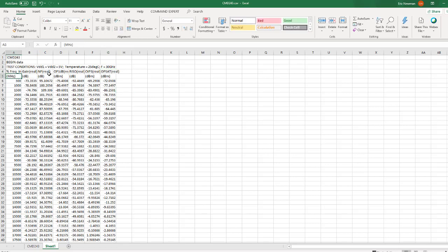Okay. Next, we're going to change the frequency range here to use hertz rather than megahertz. This is again to avoid simulator conflicts later. We're going to add that exclamation point now to this row so that the simulator doesn't try to read these units in. But I do like to change the units here to make sure people realize that this is actually in hertz now after we make the modification here.